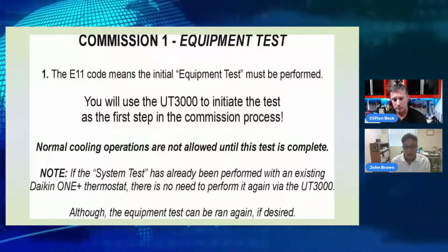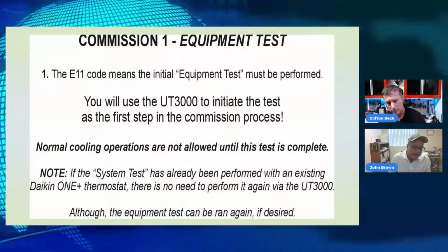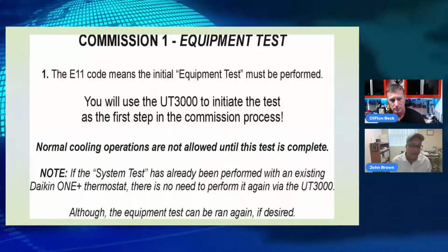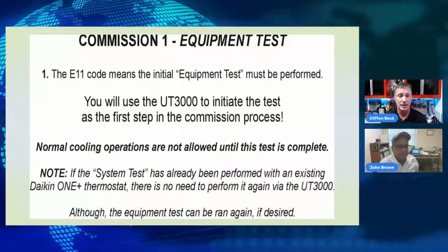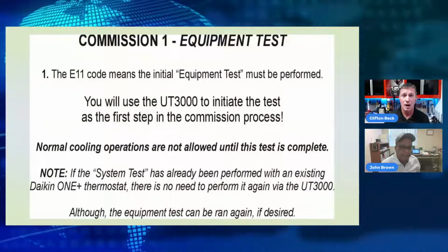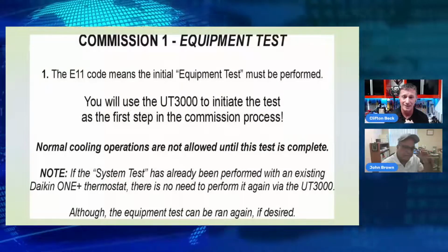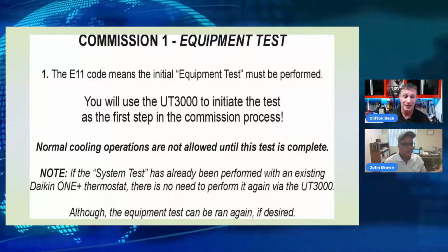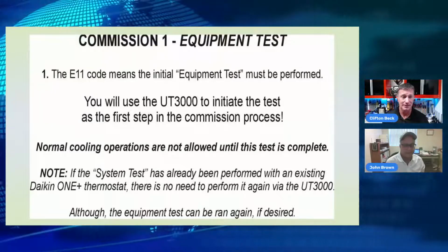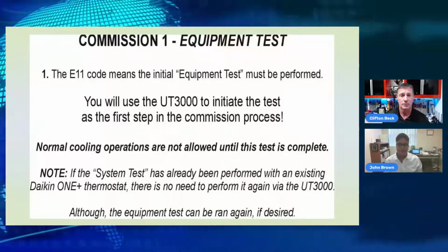Some of them are not closed, which could affect the outcome of your system test or your charging mode. Just imagine if the system itself is trying to ramp up to 100% capacity and it has dampers closed. What's that going to do to the load on the evaporator? Definitely not going to get a correct reading. Exactly.